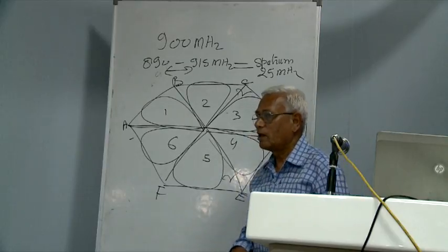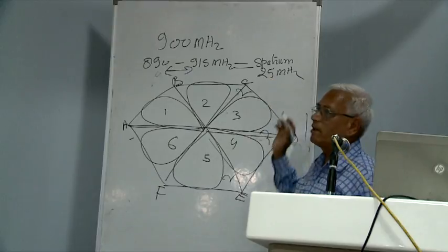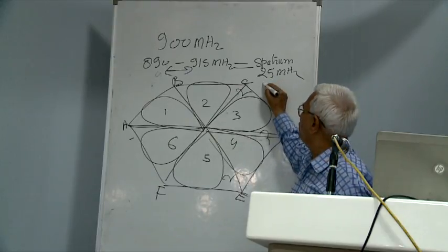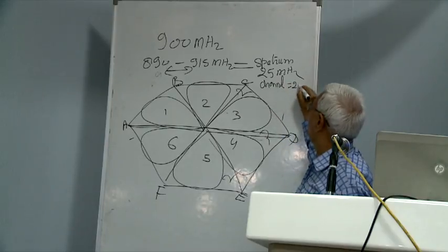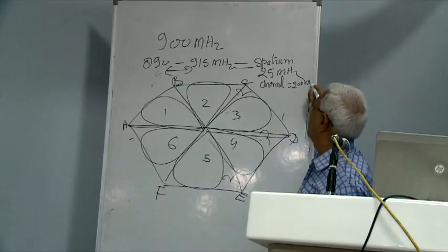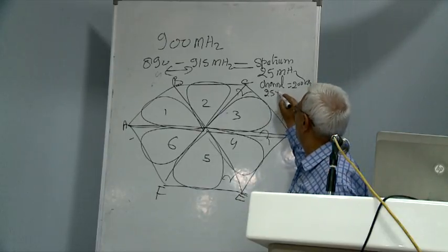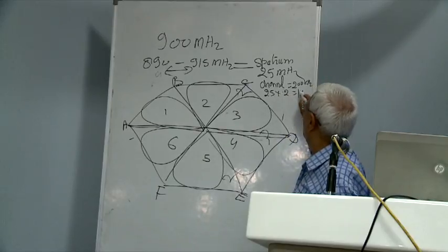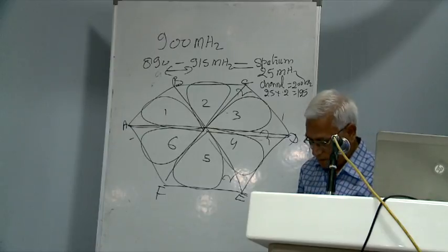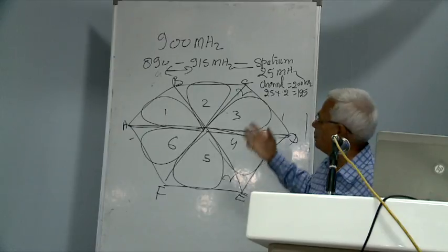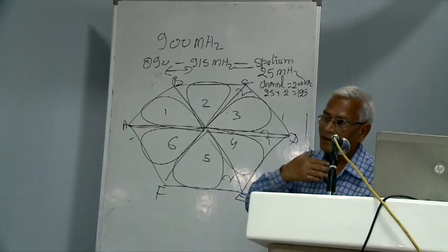And another thing, in case of mobile communication, the spectrum is 25 megahertz, and the channel is only 200 kilohertz. 200 kilohertz means 25 into 0.2 is equal to 125 channels. If everybody has the same channels, they will not be able to share. Understand? They will disturb each other.